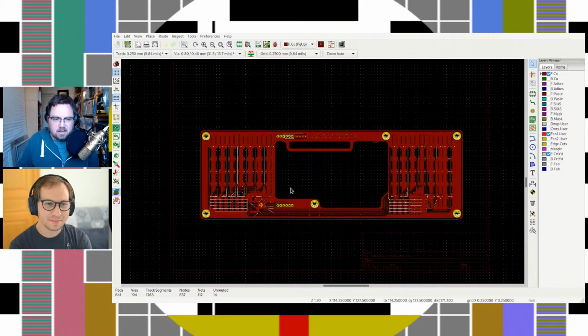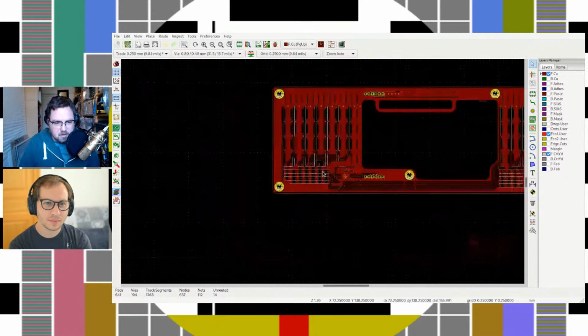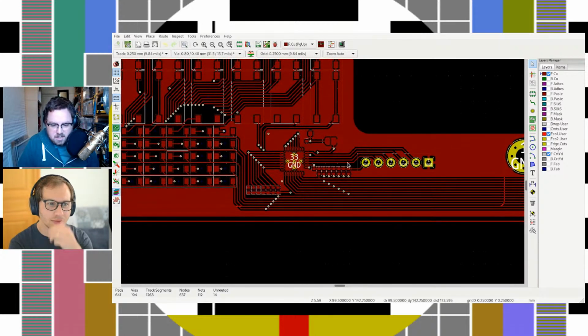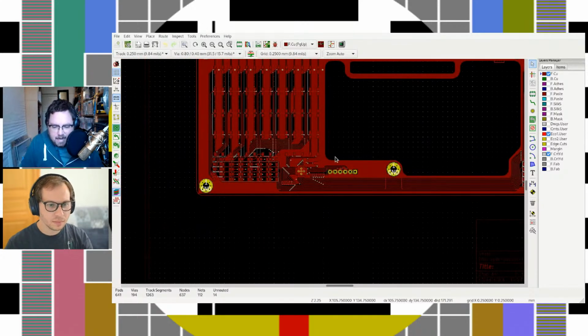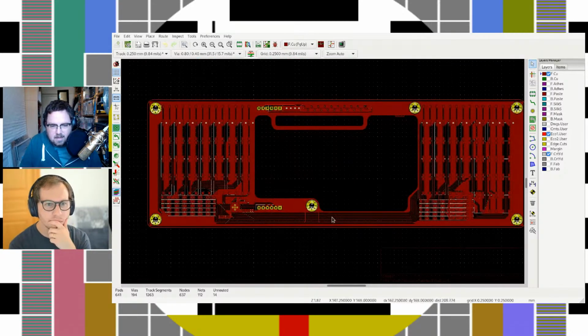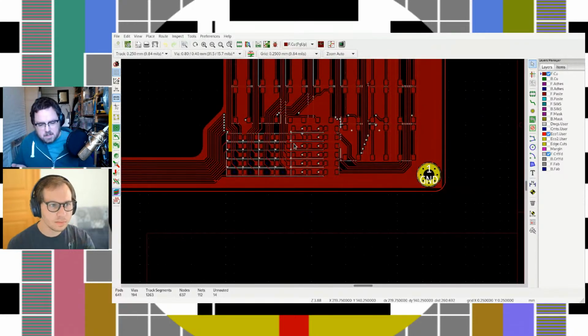But you can get just the boards with no assembly done for like 10, 15, $20 if you're willing to wait a week or 2 for the boards to show up. And then you can also, for a couple bucks more, basically the cost of parts, get stuff assembled. So I use JLC for most of this, and there's some really good tutorials out there of how to go from KiCad and all the steps you need, and how to create a bill of materials where you say, okay, I've got all these diodes, but what kind of diodes are there? And JLC will have a list of parts that they can manufacture for you.